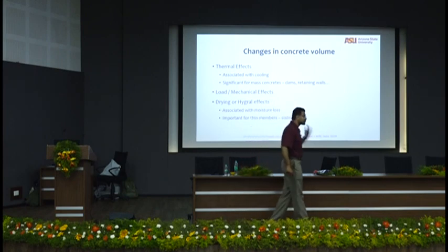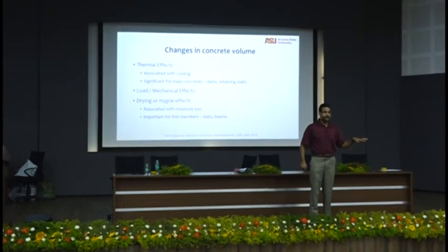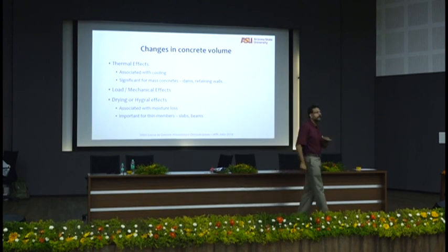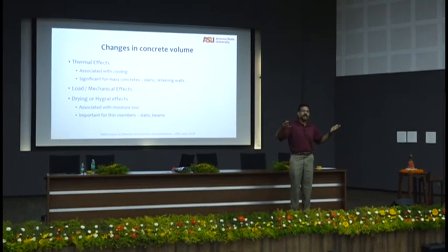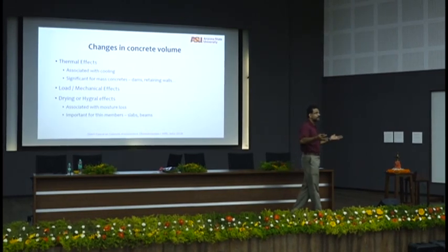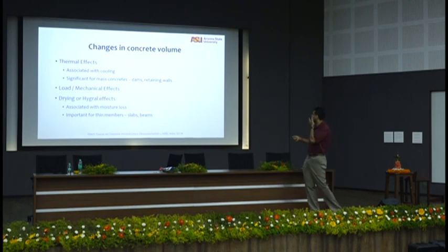Now, the idea of stresses is an idea of irregularity. If you uniformly impose a stress and the material has time to readjust, you will have much lesser damage than stress gradients or thermal gradients that cause stresses. So thermal gradients cause a lot of stresses. Load or mechanical effects can cause stress. Drying or hygral effects with moisture loss can cause stress. Thin members, slabs, you will have a lot of stress because you will